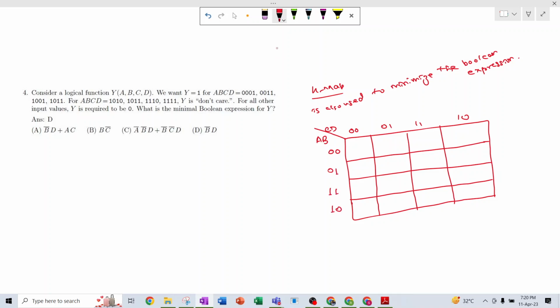That means there is only one thing in the K-map that we do. So here it is 0 0. So now this 0 changes to 1. Only one variable shifts. Okay, it is 0 1, this is 1 0. So this 0 changes to 1. Okay, and then it is 1 0. That means this variable changes to 0. So like this thing, here also 0 changes to 1, here 0 changes to 1, and here this changes to this. So that means that in this K-map we use the gray code. This is the gray code thing.